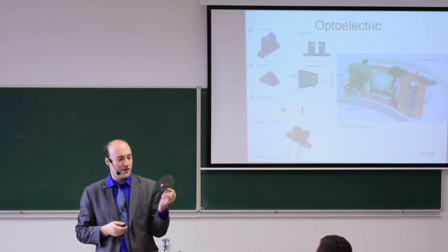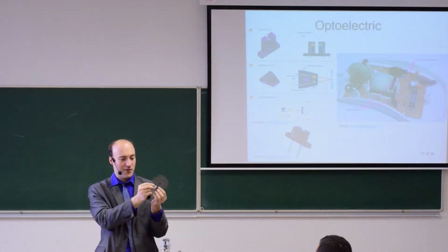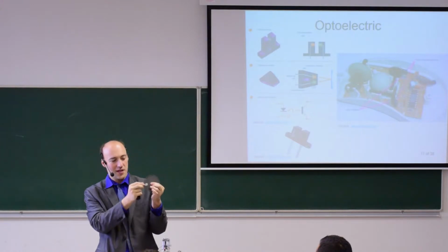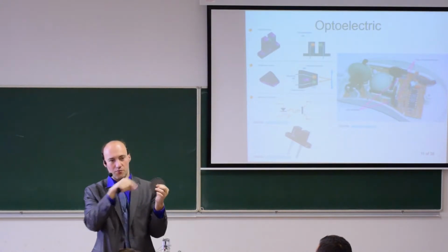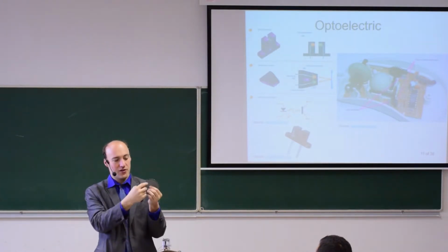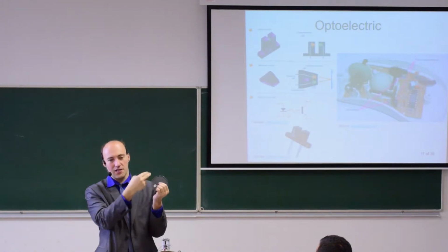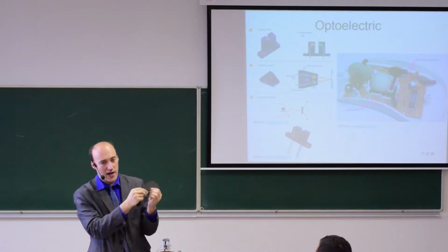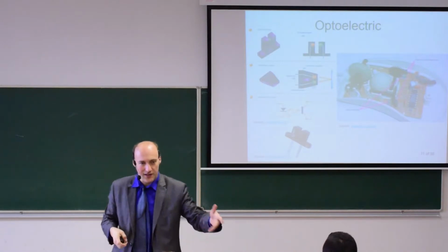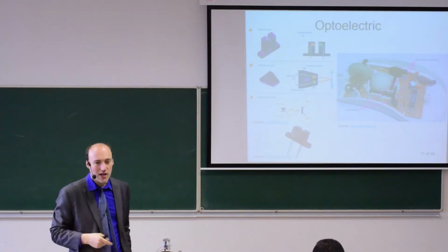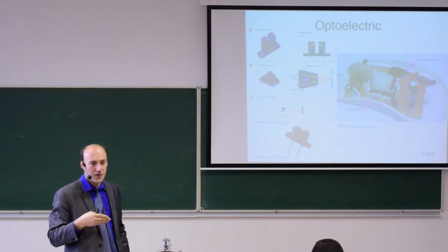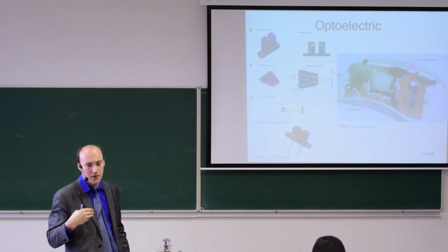Yes. We expect that if it's rotating with a constant speed, we will have constant pulses from there. And if there is one missing, we can say this is my reference position. So then by, let's say, signal processing, we can find the reference position. So we can use it also to find the zero position.